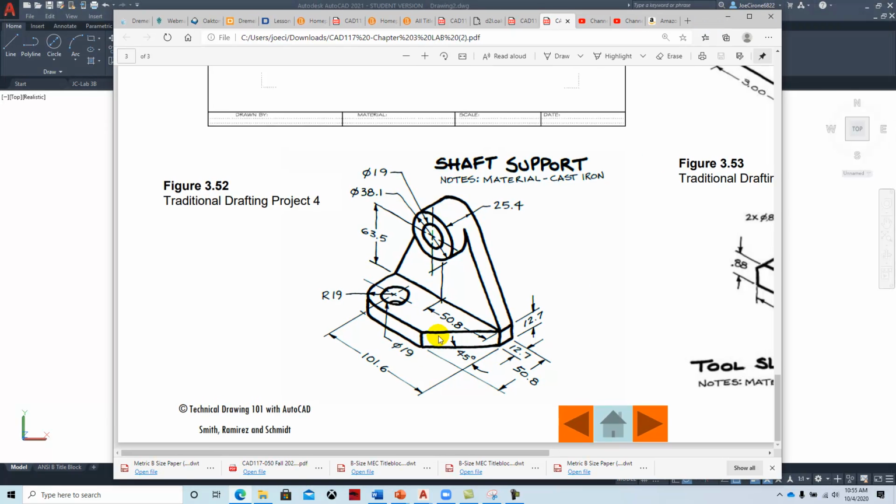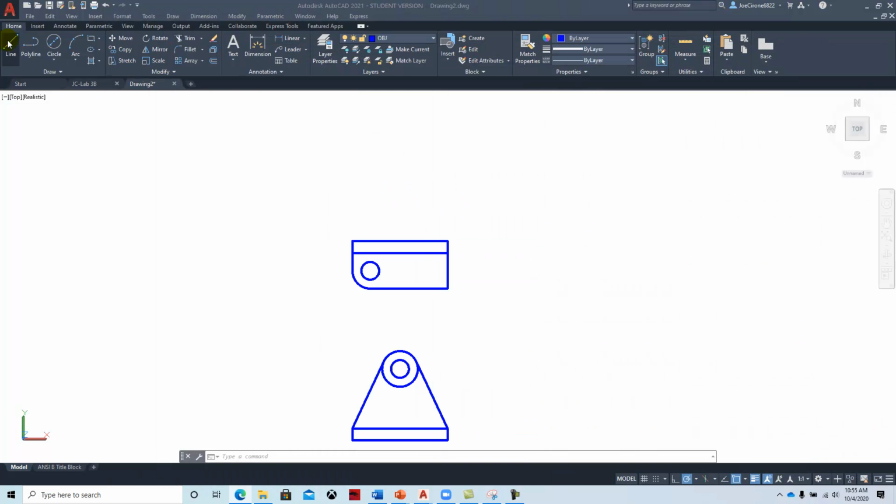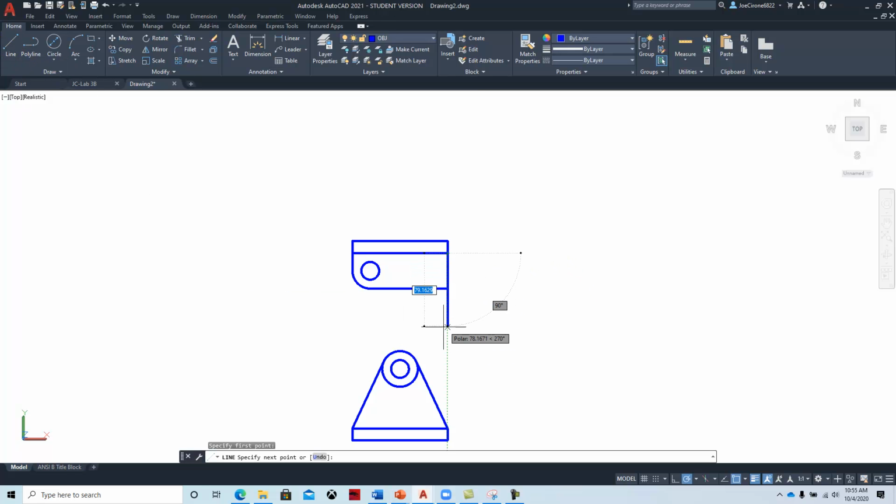And then we're going to figure this geometry at a 45-degree angle. So we'll grab the line tool, bring it right here. And if we bring that at 0 or straight down, that's 270. And then as we swing this arc, that's 15-degree measurement. That's 2, that would be 30. That's 3, that would be 45. So it would be 225 degrees. And then we'll trim that.